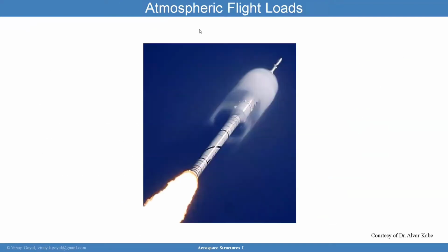I want to talk a little bit now about atmospheric flight loads. Let me discuss atmospheric flight loads a little bit. And this design condition does occur for the majority of the portion of the launch vehicle. Atmospheric flight loads are predicted by combining the results of separate analyses. The analyses in this case are performed at discrete times in flight with models that represent the coupled system at the analysis time of flight, because the vehicle is changing due to the mass that's been expended.